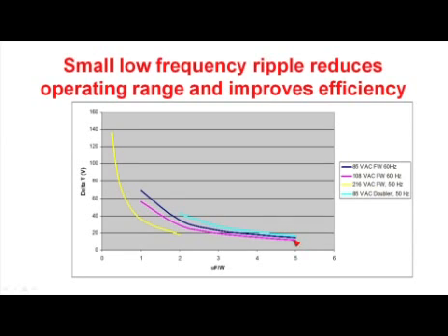I've done various configurations of the input capacitors here. I've done an 85 volt input AC that you might see in Japan. I've done a 216 volt input that you might see in Europe. And then I've done a 108 volt input like you might see low line in the US, and plotted capacitances versus the change in capacitor voltage at low line.